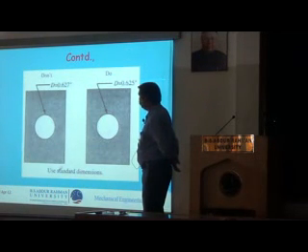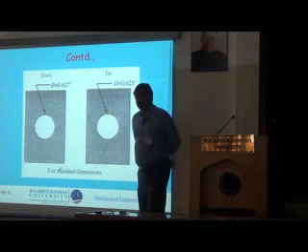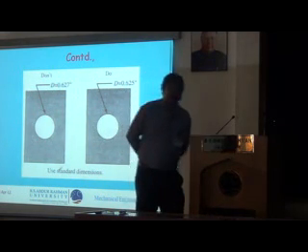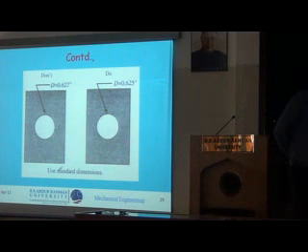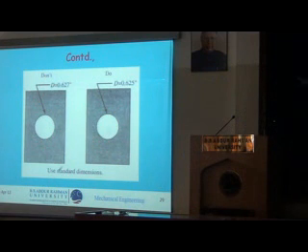Now, when you make holes, the drill bits are available only in standard sizes. So don't go for odd sizes. Even now we are following the British drills as well as the international standard drill bits. Now you should use, wherever possible, holes of standard diameters only.